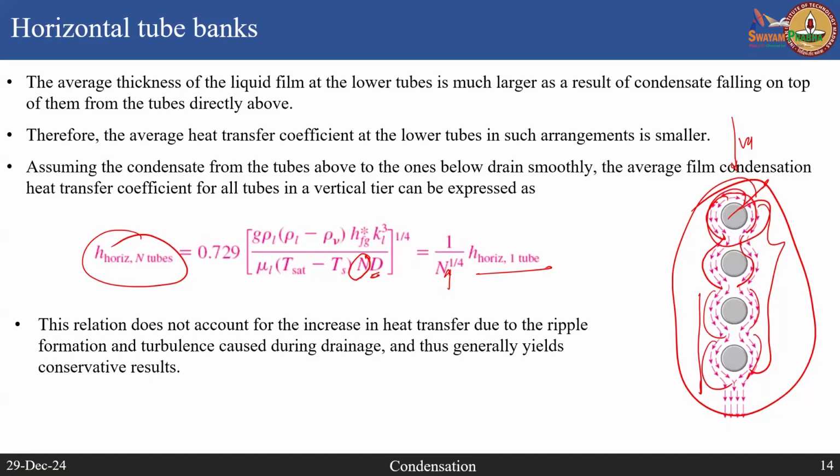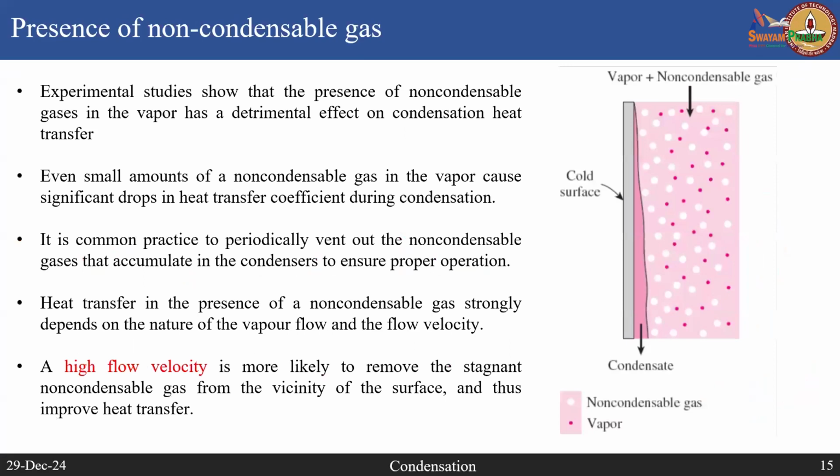So this is for both film and drop, or only film? This is only film. Whatever I am talking about now, the theory, is all assuming that it is film condensation. So for drop wise condensation there is no theory.